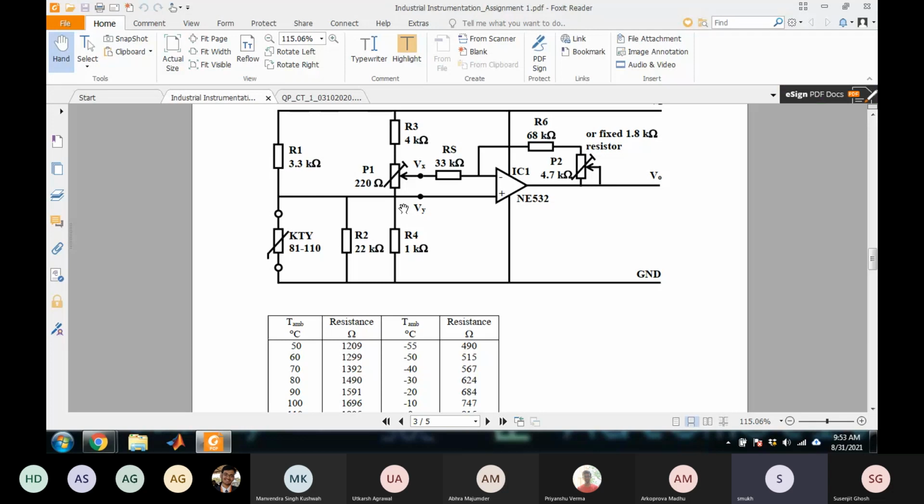That will be the feedback resistance value, and the input resistance value will be 33 plus the source resistance, that is the Thevenin's equivalent of this circuit seen looking into this circuit. So that's how the gain has to be calculated. It's interesting, you have to think about it.